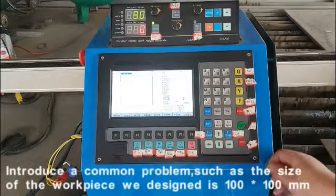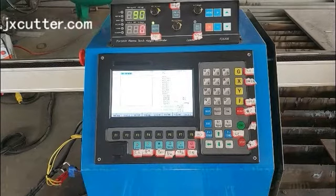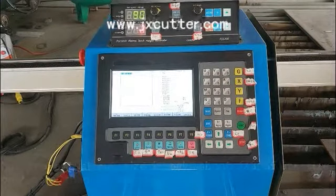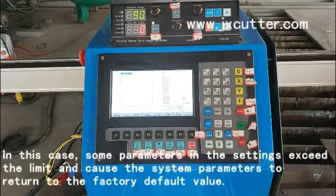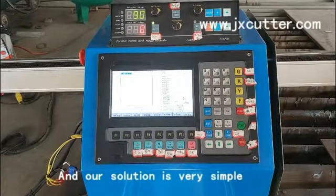A common problem: the size of the workpiece we designed is 100 × 100 mm, but the actual cut size is only about 1/3 of that, only more than 30 mm. In this case, some parameters in the settings exceed the limit and cause the system parameters to return to the factory default values. And our solution is very simple.